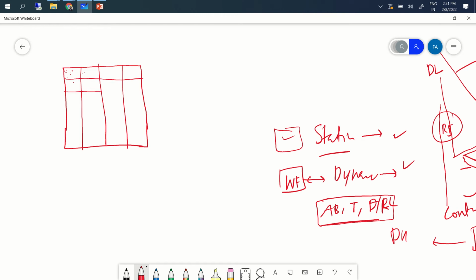And there is a standard requirement as well for what the size of these grids should be where measurements can be taken. So at all these intersections, or rather only at these intersection points, lux levels or light levels are taken, and the data is interpolated for the rest of the space.